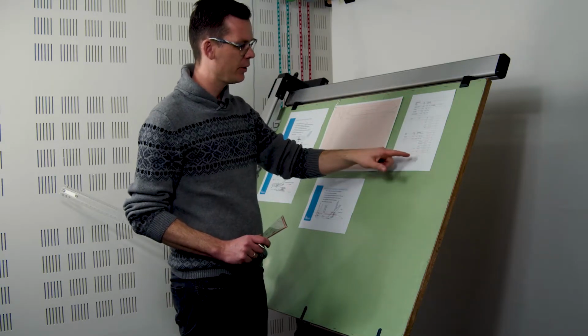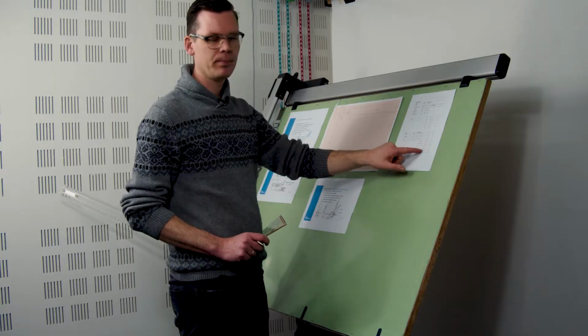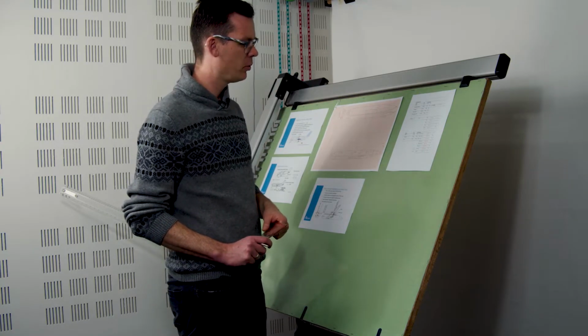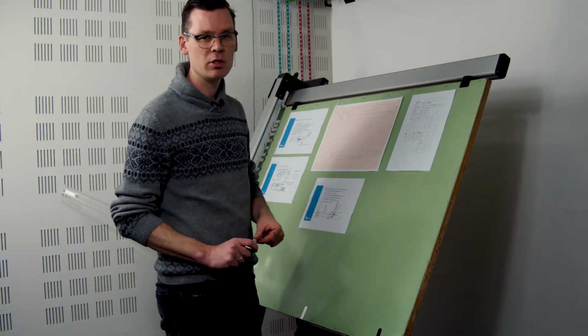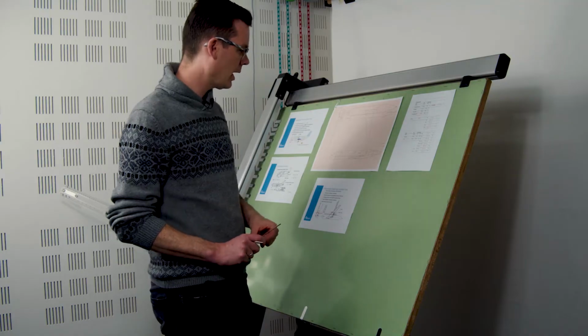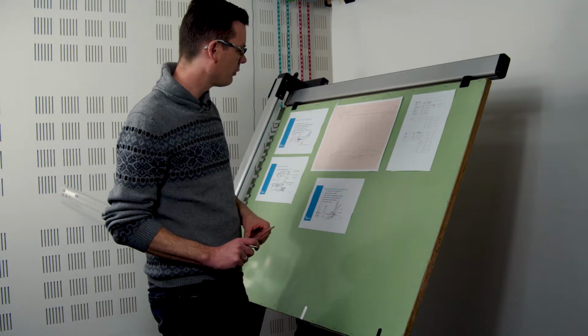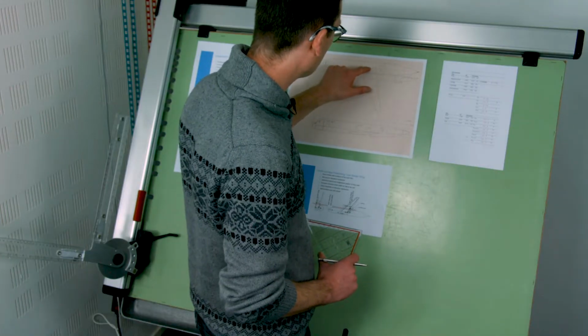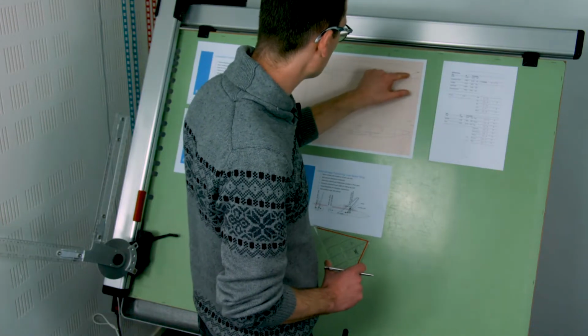All the calculations were performed and the sheet has been filled out. From this sheet I'm starting with the drawing of the most forward and most aft CG location that result from this analysis of the CG excursion. I do that first of all in the top view, where I already drew in the center line of the airplane.